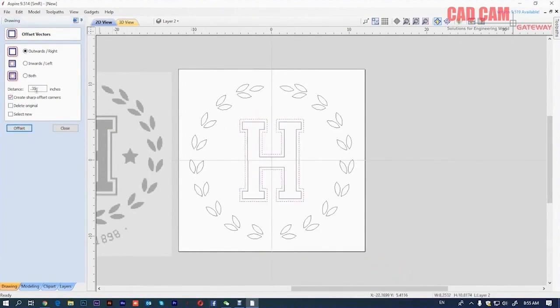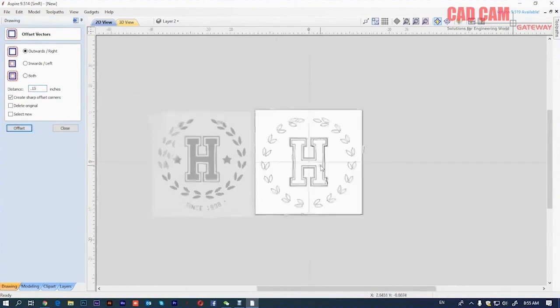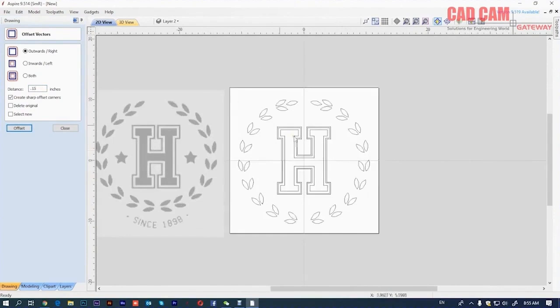Similarly, offset it one more step outside. I am offsetting it by 0.15. And make sure to select the sharp corner. And this object is also drawn outside. So in this way, this small exercise is complete. With this exercise,